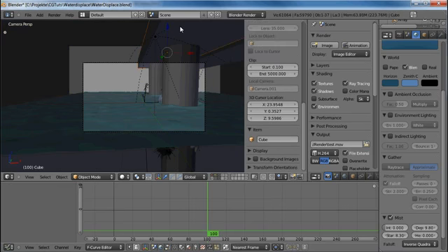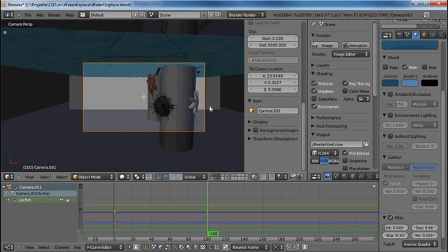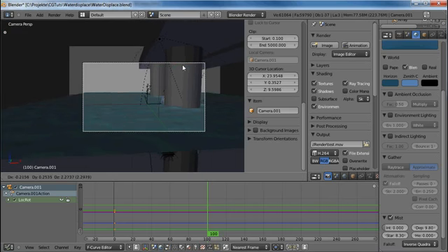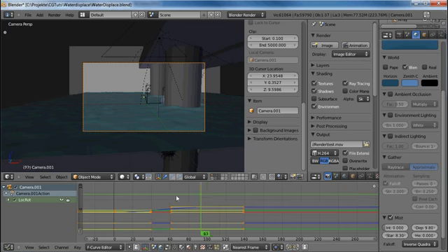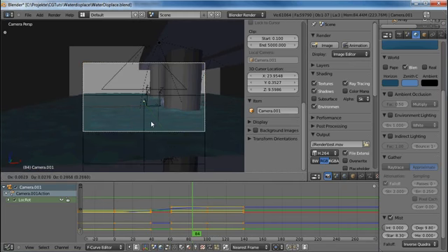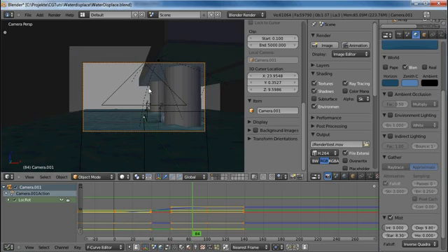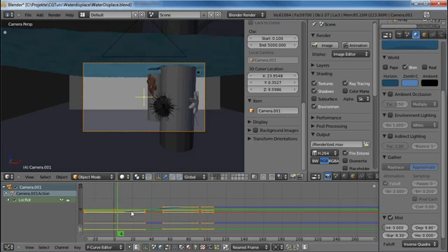Actually, if we unhide our planks here, it's okay, if you move the timeline and you don't have a keyframe set, Blender will automatically update using the last keyframe. So G to move it across the water surface, I to insert a location rotation keyframe again, and it's always a good idea if you have an animation to overshoot. That means we are going a bit too high, and Shift F to rotate it a bit upwards, and insert a location rotation keyframe again.